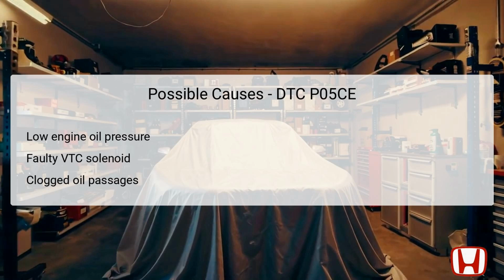First, low engine oil pressure can significantly affect the ability of the VTC system to operate correctly, as oil pressure is crucial for the actuation of the VTC solenoids. If the oil pressure is inadequate, the phase control may lag, resulting in a fault.